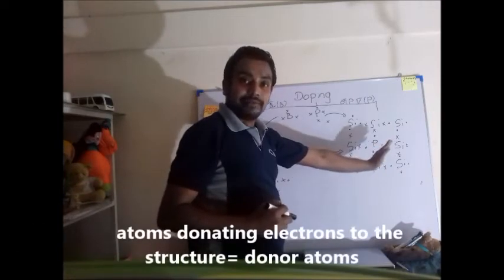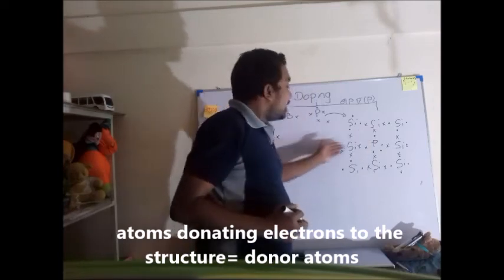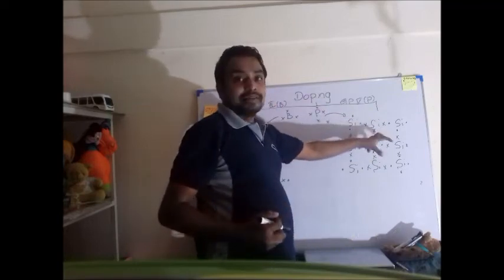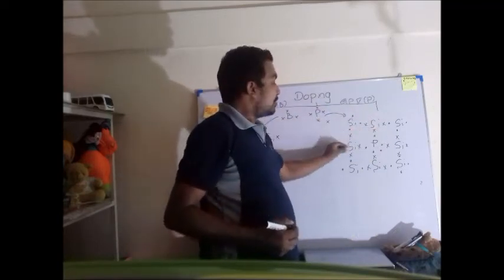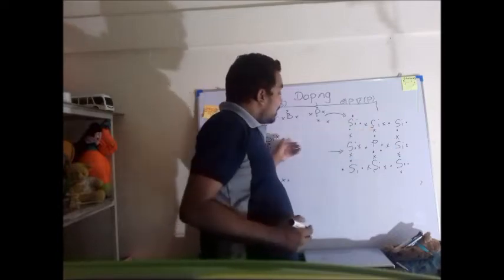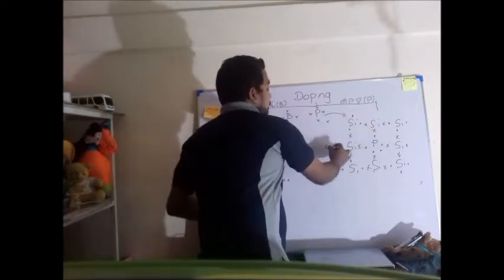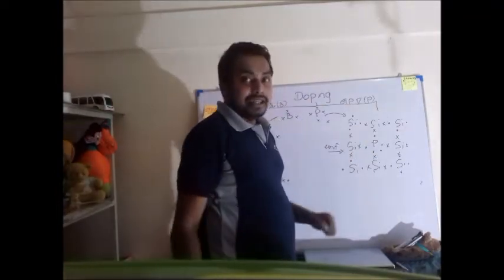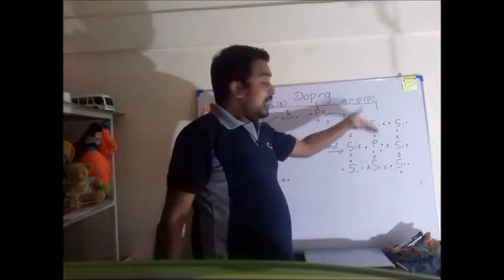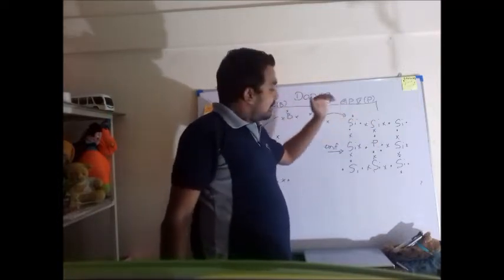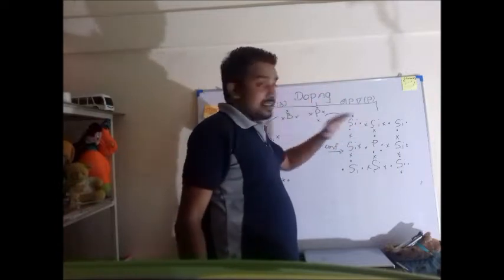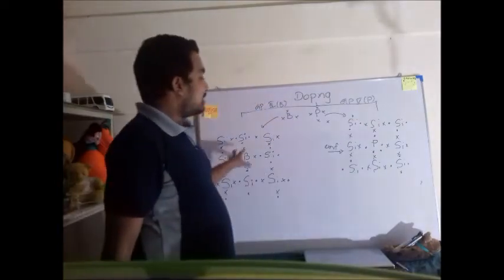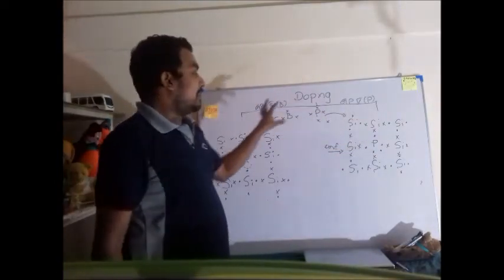Electromotive force is applied from this side. There are not only one atom but many phosphorus atoms included in this extrinsic semiconductor. So there are many free electrons. When the electromotive force, EMF, is applied from this side, those free electrons can conduct electric current. There are free electrons present in this structure. The conductivity is somewhat stable, and we can use them in our electronic circuits. That is how the extrinsic semiconductors are produced.